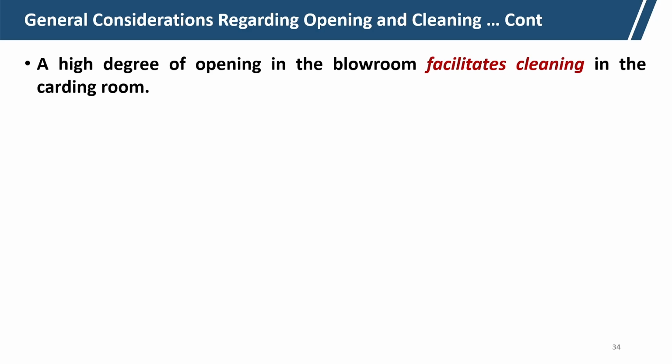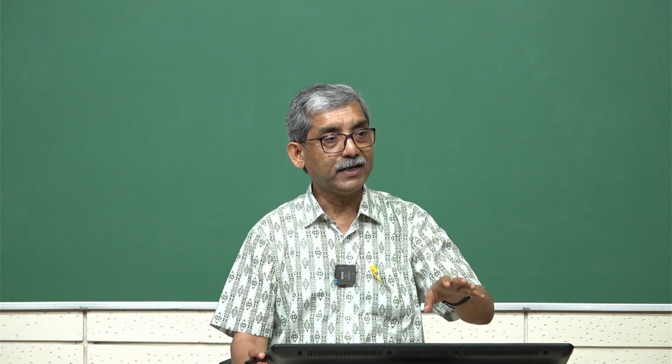A high degree of opening in the blow room facilitates cleaning in the carding room. That means we should concentrate on opening at the blow room, and cleaning should be the secondary function, okay, in the blow room, because if we can open better in the blow room, that will help cleaning in the carding.